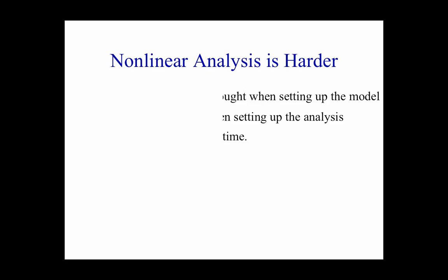That takes a lot more computational time. When you do nonlinear analysis, we're doing Newton-Raphson iterations. We're doing 10 steps, say, per iteration. So things take a lot longer to run. It does not always converge. You will not always get a solution for your model, depending on what your input model was and how you did the nonlinear analysis. You are not guaranteed that it's always going to work.